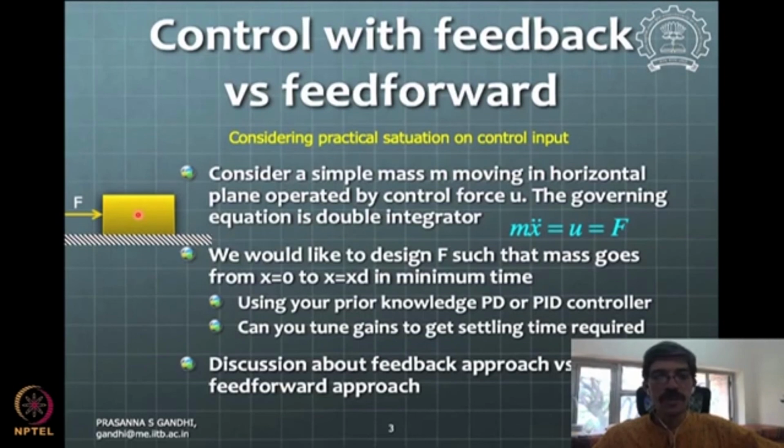So in effect, what we need is some combination of these two strategies. We'll give the force which is required to go from here to here according to the planned trajectory, and in addition, beyond this feed forward control application, whatever we still want to control is where we add our feedback control.